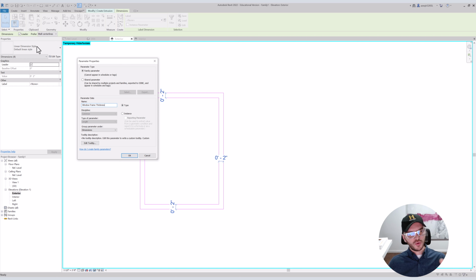As you know, when you go and select a different family type from your properties bar, let's say you want to change from a 3-foot door to a 3'6" door, whatever. If you have an instance, you don't have to create a new family because, why am I explaining? I'll just show you. We're going to create it. We're going to make this a type.